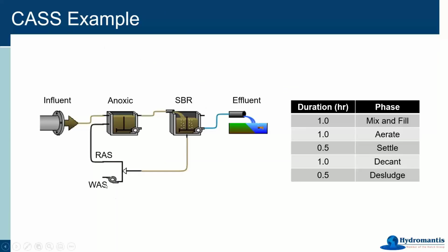So in a CAS system, what you're also doing is putting another tank up front, such as this, and actually recycling some of the sludge back to this tank. That's how it differs from some of the other SBR operations. So as you're desludging here, you're wasting and recycling with this one flow. And what I'm recommending, what we used, is a control splitter. It's at the bottom of the flow splitting options in the GPS-X unit process table.